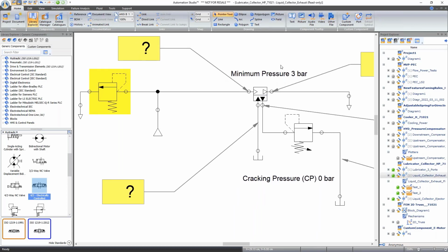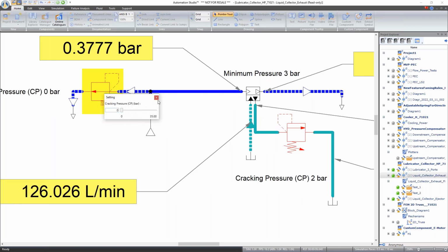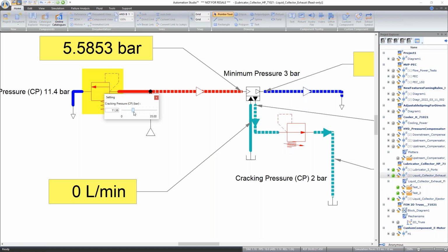It has a setting pressure, in this case set to 3 bar, and that is combined with whatever pressure is at the outlet. Normally you would never relieve here, but just for the demonstration, we're going to add in 2 bar cracking pressure on here. Now we would just reset this to 0. The way this will work, we have the pneumatic flow running through here. We have our chamber here, which is full of oil. As I increase my pressure, once I get past 5 bar, you'll see that oil is evacuated through here. And then when I drop below 5 bar again, you can see it suctions back in more. As I continue, you would suction and pump the fluid from the hydraulic line.